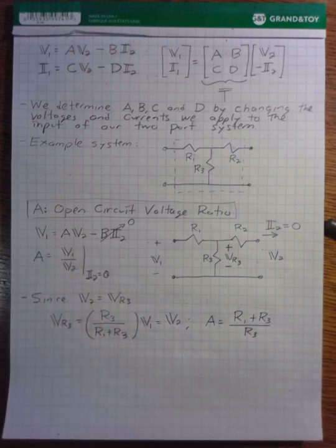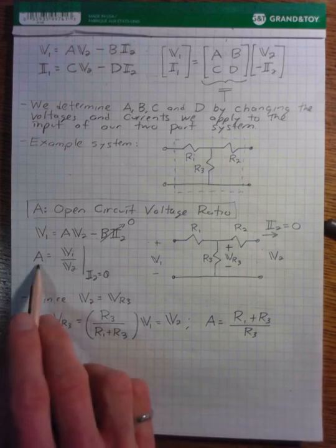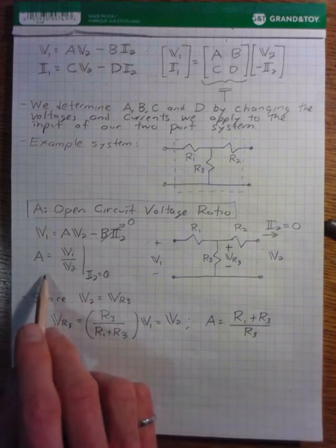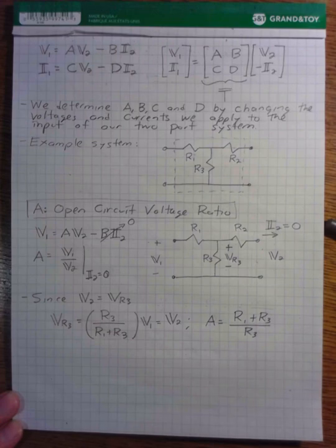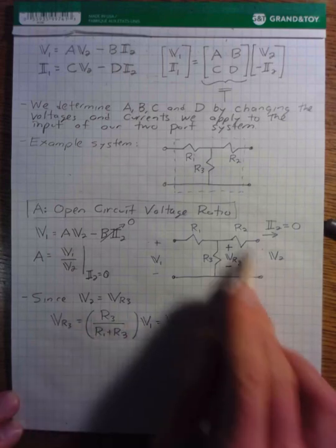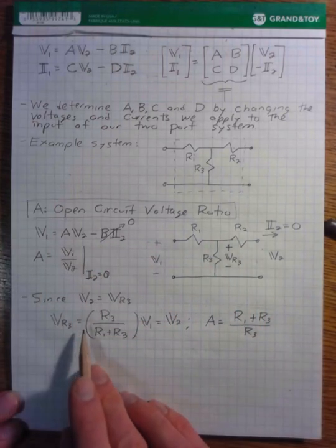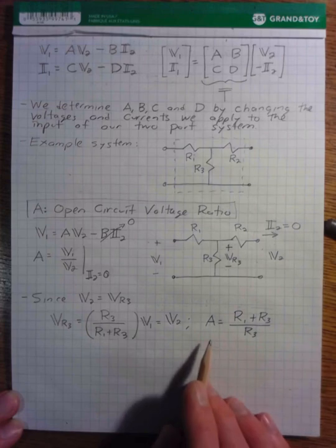So we're working with these ABCD parameters for a bit here, and it's not immediately obvious how these are going to make our lives easier. But once we actually do start cascading our systems together, then we are going to basically use this A parameter to determine the voltage transfer function of a bunch of systems all cascaded together. But there'll be more on that later. Okay, so this is how we used our analysis, voltage divider and all that, to determine our parameter A.